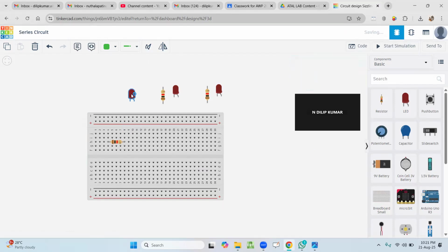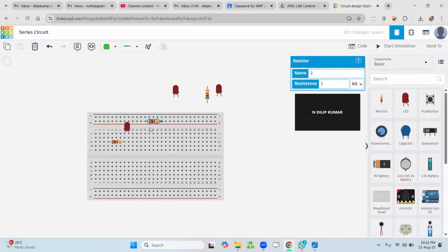In order to make that convenient, we have an option in the panel, the interchange mirroring option. Click that option, and the anode and cathode terminals will be interchanged. Then place the LED in series with the resistor. You can see if I place the mouse pointer here on the breadboard, this whole vertical line is shorted in the breadboard.